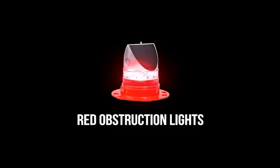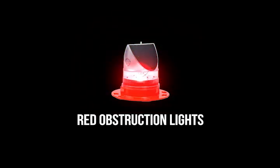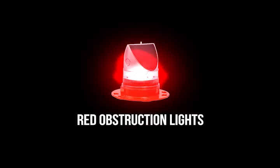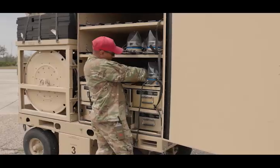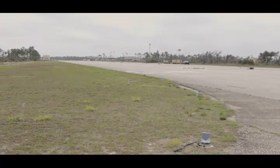Obstruction lights are red and used to mark any hazard on the airfield that could cause damage to aircraft. These are solar-powered, but can also be charged via the AC line. Taxiway lights use the AV70 frame, which is self-contained with solar and removable battery. Place 2 lights 5 feet apart at each taxiway entrance, 2 feet off the edge.